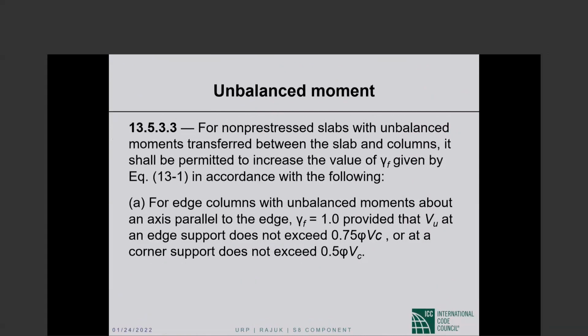So let us recap. The topic we are discussing is unbalanced moment transfer. I told you under gravity, it is pretty limited unbalanced moment transfer except at the exterior support. Under lateral load, that is not the case. There is significant unbalanced moment transfer at every support.